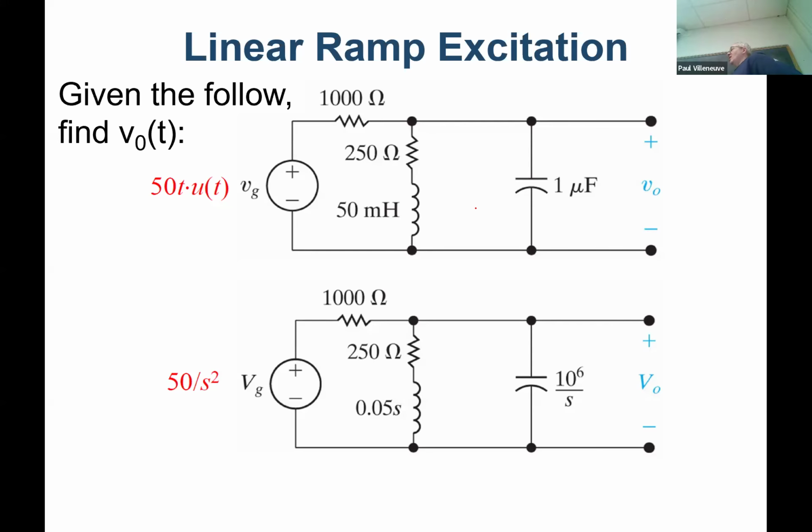But again, because of things like your power supplies, right? I've got my laptop power supply here. It's a little plastic blob, and inside it's a bunch of semiconductors. They used to only have power supplies with transformers, so a power supply was the size of your hand and weighed a ton, because inside there was a transformer that would smooth out a lot of the operation.